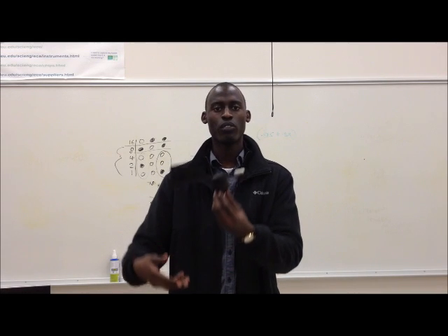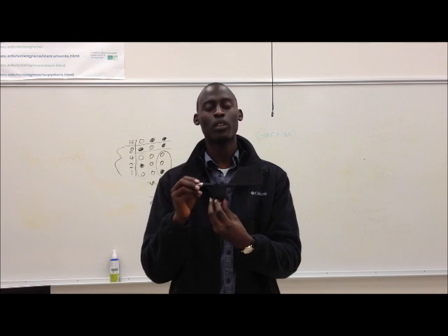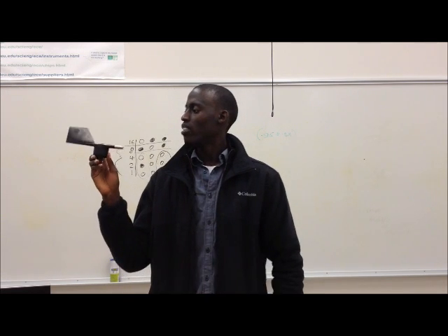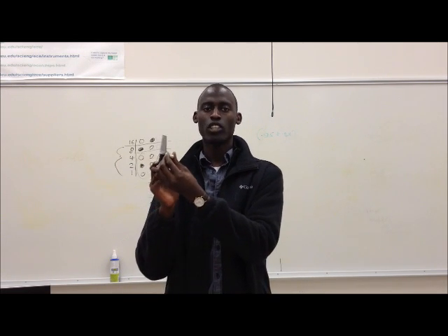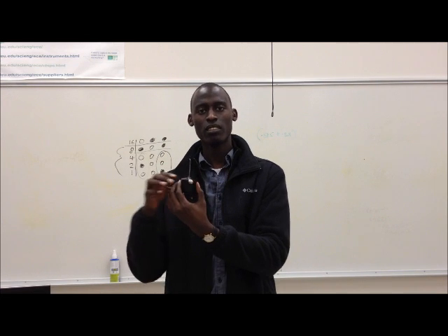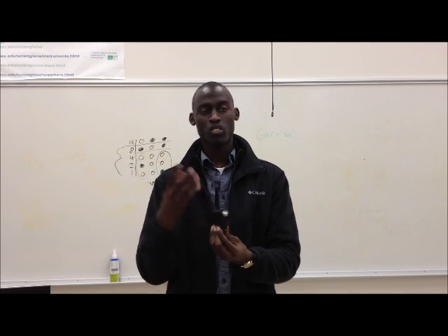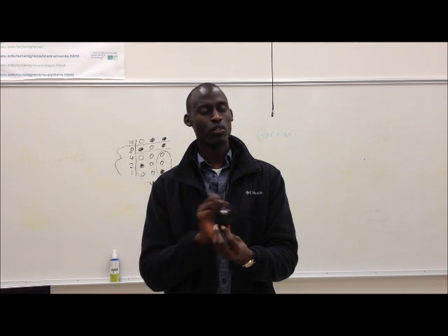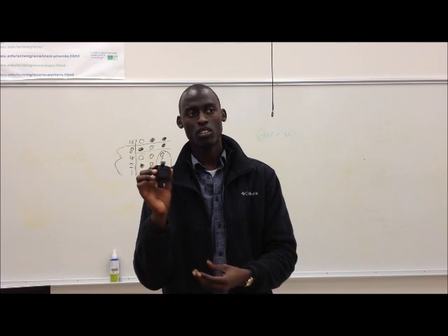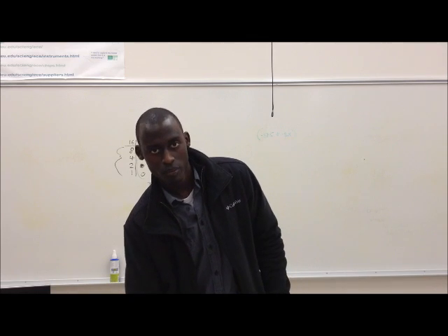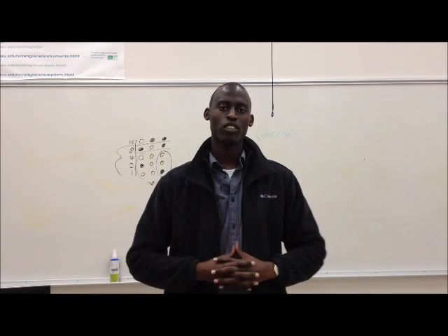This here is a wind vane which we'll use to find the direction of the wind. As this travels through the wind, it points in the direction of the wind. Inside here is a potentiometer whose resistance varies depending on the direction of the wind vane. And using the resistance in this, we can compute the direction of the wind.